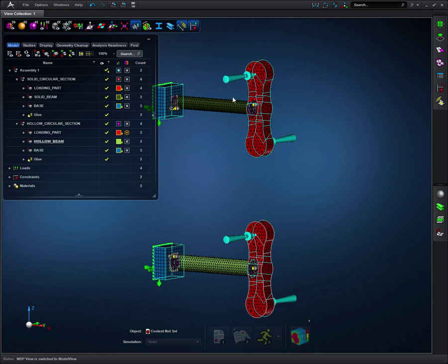In both beams, we apply a 1 Newton force on the tool in opposite directions to induce a torque in the beam. With a moment arm length of 0.10909 meters, this translates to a bending moment of 0.218 Newton meters on each beam.